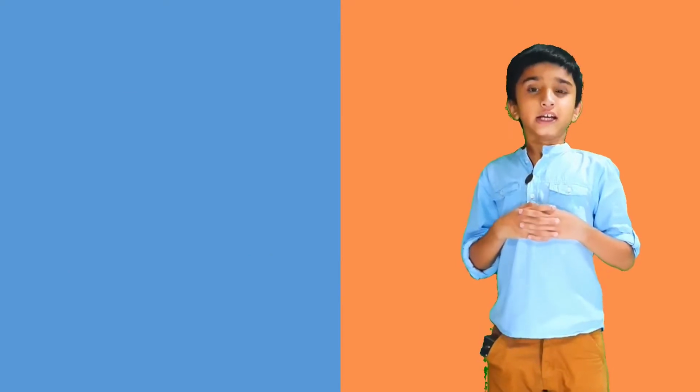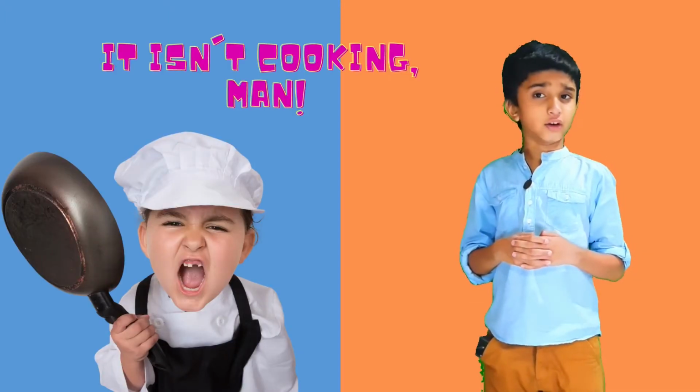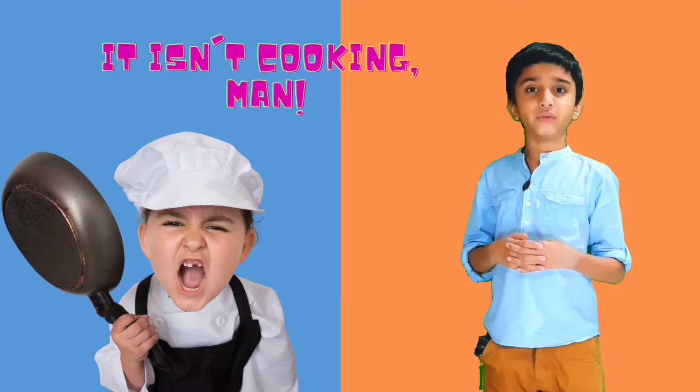Remember the induction cooktop we saw? It worked on 230 volt AC. If I take this cooktop to the US, it will power on, but it will not heat enough, as in the US the voltage level is 110 volt AC.